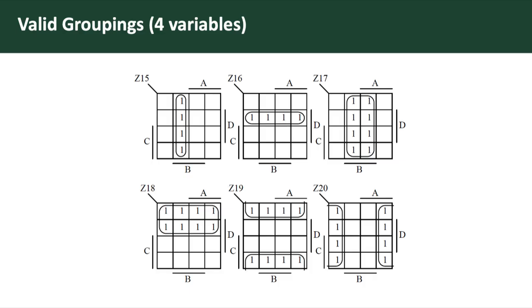I want you to internalize that the valid shapes are not as restrictive as they might seem. Because of the torus-like adjacency structure of the K-map, many shapes that look disconnected on the flat grid are in fact rectangles when you account for wraparound. The test is always: do all cells in my proposed group form a rectangle, possibly with wraparound, and is the size a power of 2?